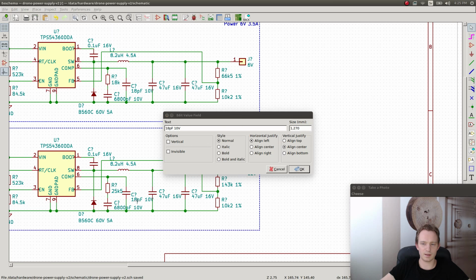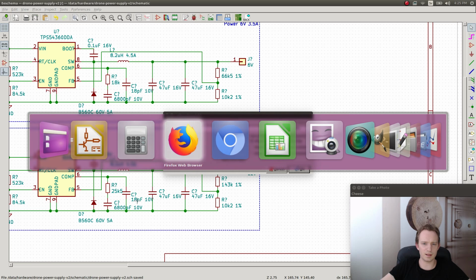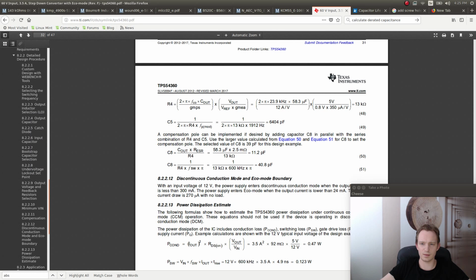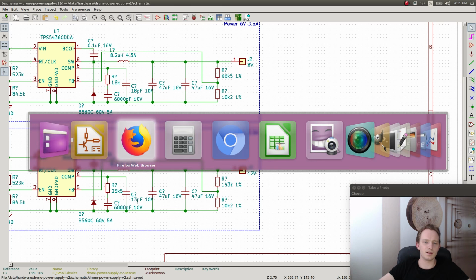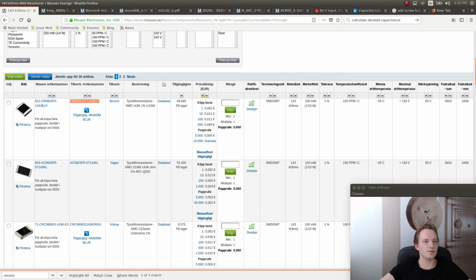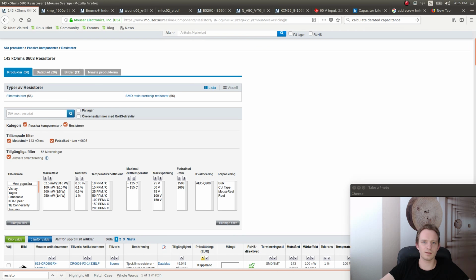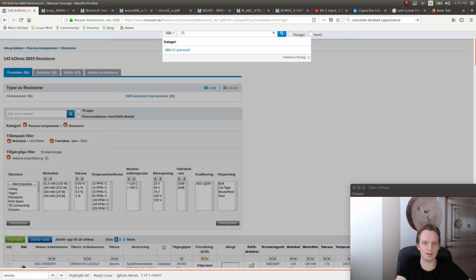And is that like the maximum value or what? Right, so they choose a little bit smaller capacitor. So let's choose 13 picofarads. And let's try to find a capacitor that we can use for that. So 13 picofarads, it doesn't sound like it's a standard value.